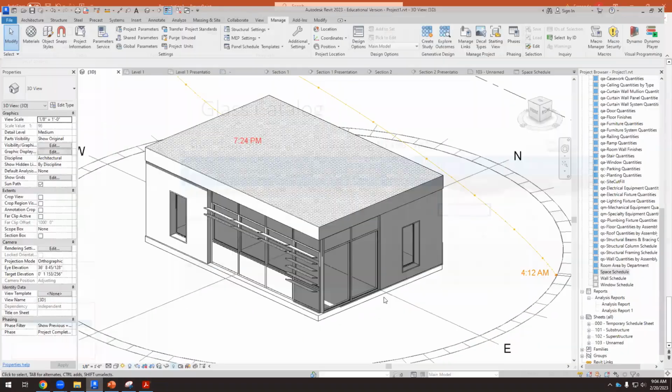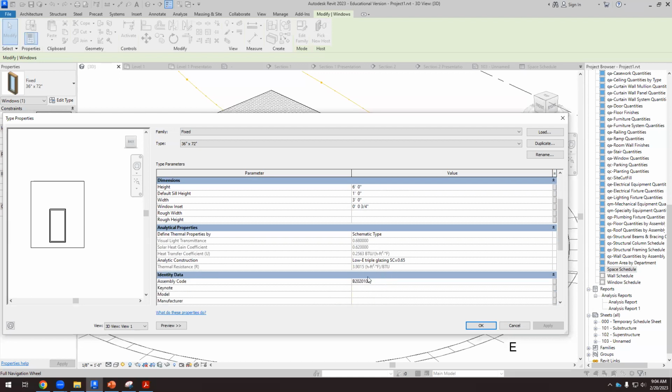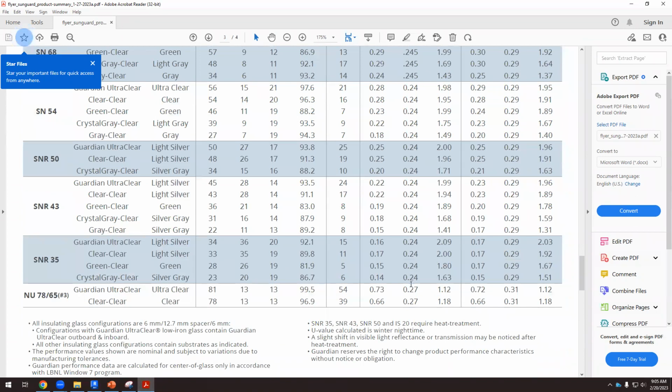And then you have to go to Revit. So if in Revit we have selected this triple glazing with the solar heat gain coefficient of 0.65, here we have the heat transfer coefficient U, it's 0.25. Okay. So I think the one that we found here. Yeah, so this is 0.27, it's not 0.25, but it's close enough. And the solar heat gain coefficient, it's 0.66. So that would be something similar to the glass that we have in Revit.